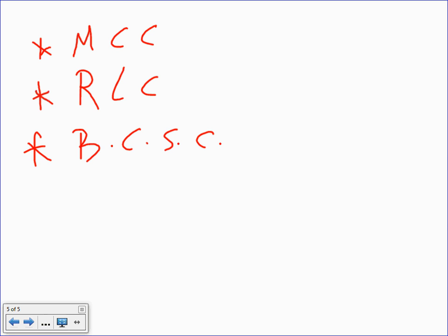These two guys, this is basically the full load current of the equipment. If you remember, what we did, we used one of them and you multiply this by 1.25, but the manufacturers already did that for you and put it as the ampacity, so don't worry about it. So these two are your full load current: rated load current, branch circuit selection current. The manufacturers do some experiments on their equipment, they run them and they say, here's the amps that this equipment, when it's up and running, is going to consume between the compressor and the fans.